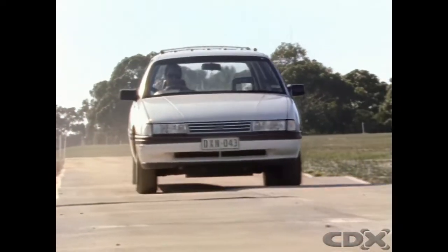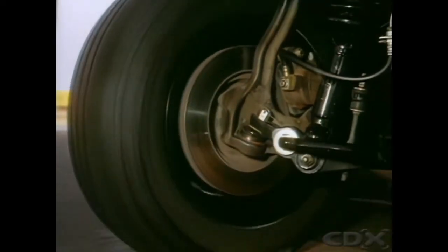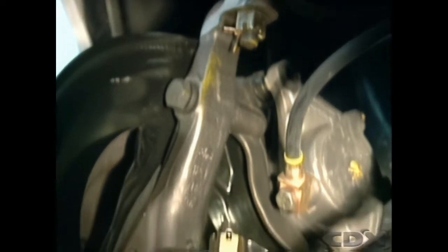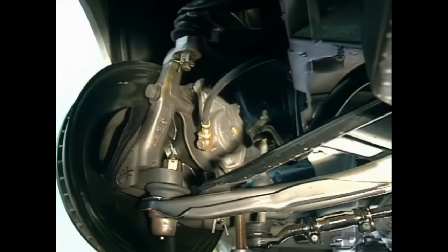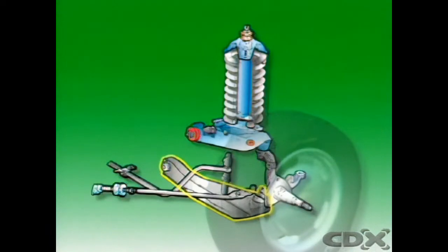Front suspension systems are normally independent, but in addition to their suspension function, they have to allow for swiveling of the front wheels during steering. This is catered for by ball joints or bearings that also allow for suspension movement. The ball joints locate the wheel assemblies on lateral wishbones or control arms. Depending on the design and the location of the springs, the lower arm may be a wishbone with 2 pivot points or a control arm with 1 pivot point.